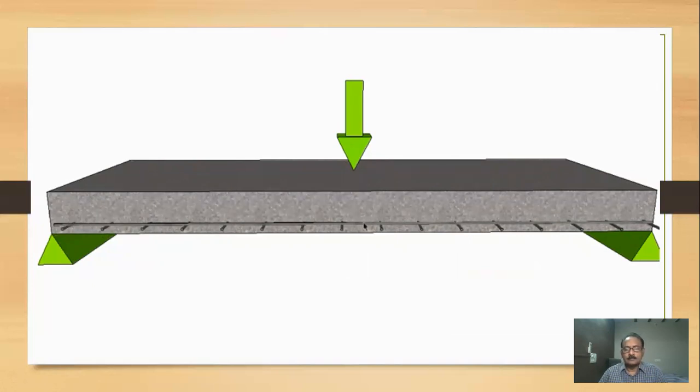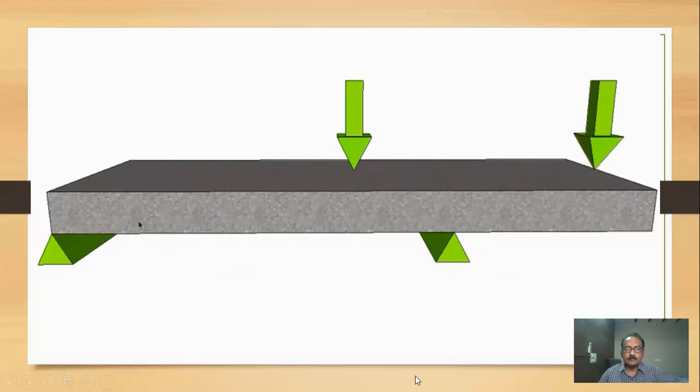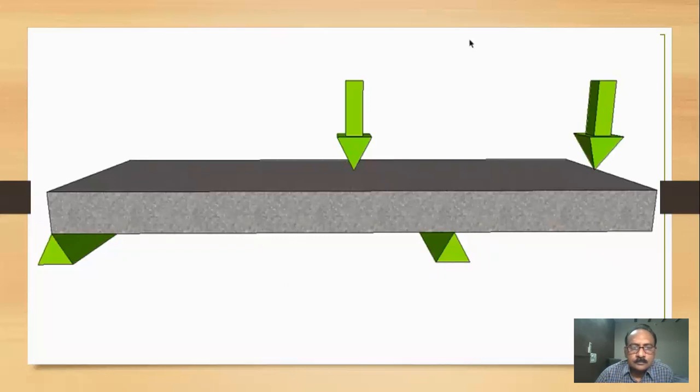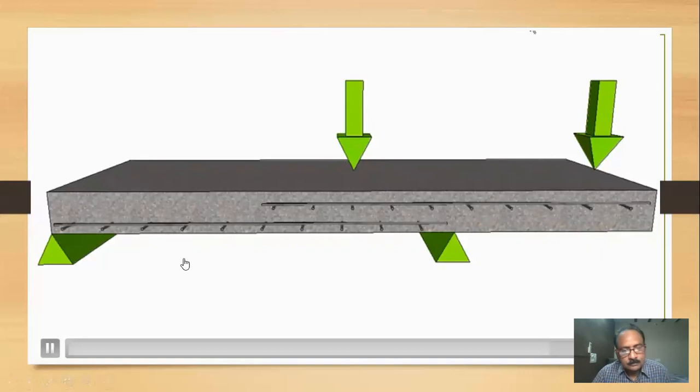Now, as I said before, this is where structural engineers make their money, because there's going to be lots of different situations where we're going to have different loads and different scenarios. In this instance, such as a cantilever, we've got a load down in the middle, and again we're going to have the self-weight of the slab plus anything else we're going to put out here on this end of the slab, causing a load out here. So there's actually going to be a bend over that support and a bend in here as well.